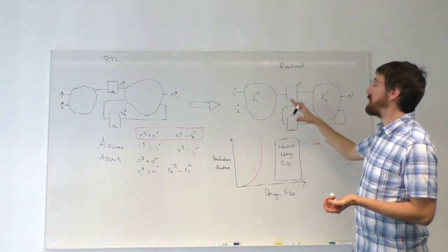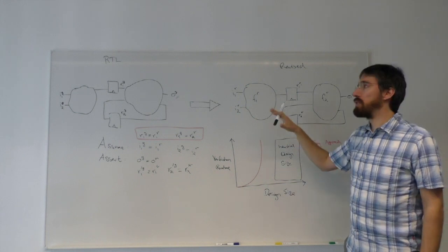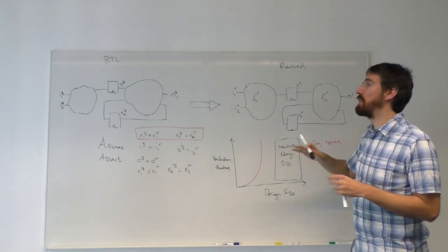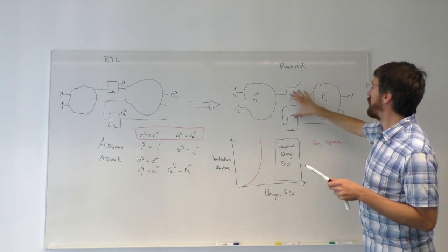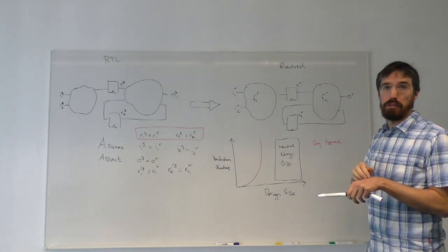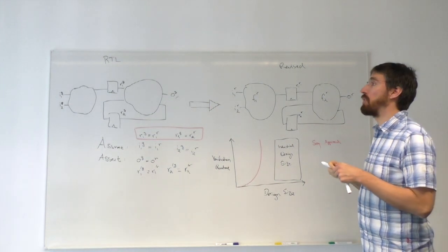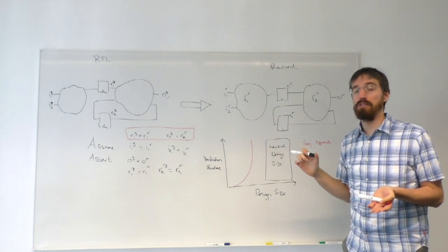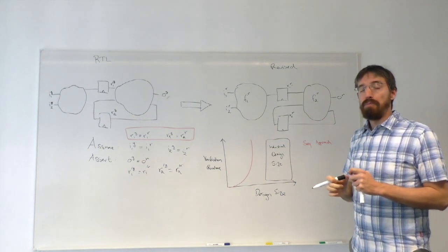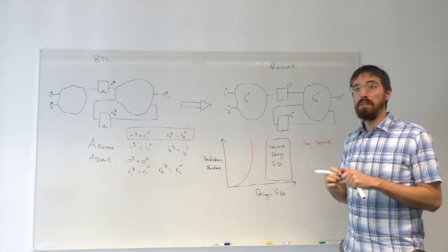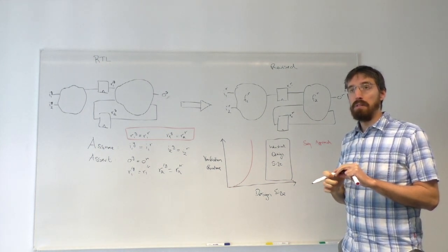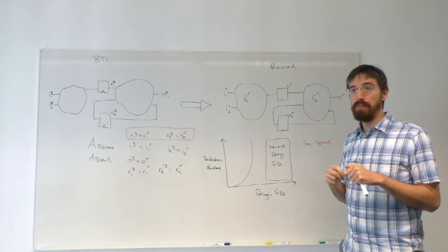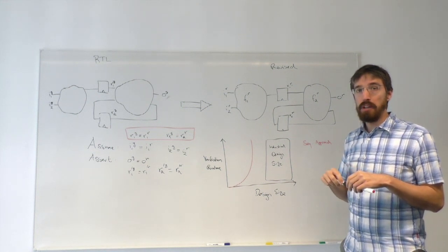Also, an implementation tool generally does not preserve the structure completely, so it may actually move flops around. For instance, a common scheme would be that these two flops would be moved after this logic cloud, which would typically be referred to as retiming, or even more complex optimizations. For instance, a shift register could be transformed into a RAM implementation or something of the like. This is basically not for beginners. You really do have to understand what you're doing with these tools, and really understand the code, where the problems potentially can be, and how to optimize along the way.